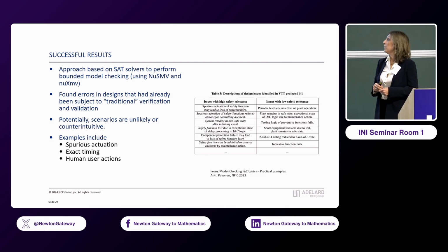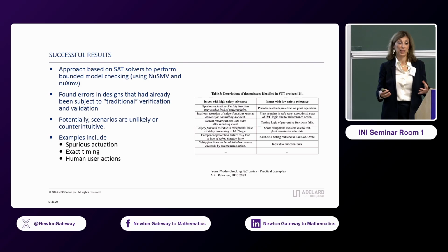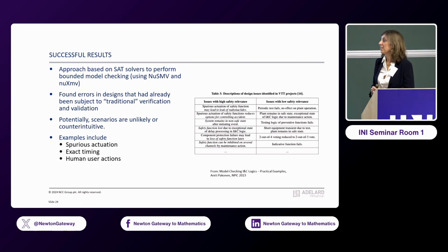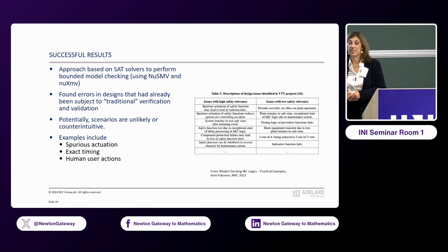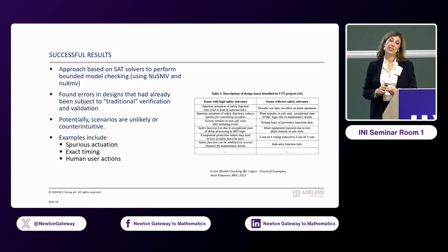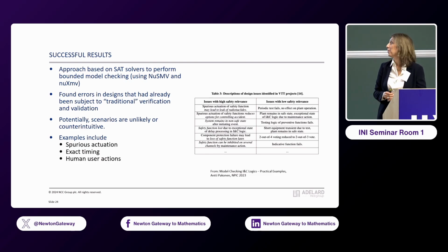But I think the most exciting thing is really the work that has been done in Finland. In Finland, they've been using model checking for a few years now on proving the application that runs on the PLCs for the most critical systems. And it's model checking with SAT solvers. They found errors that hadn't been found using the normal verification activity, which is very heavily based on testing.